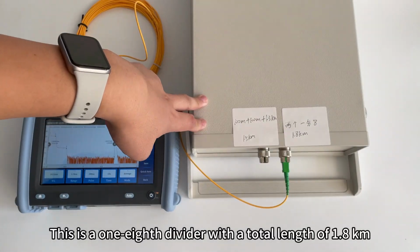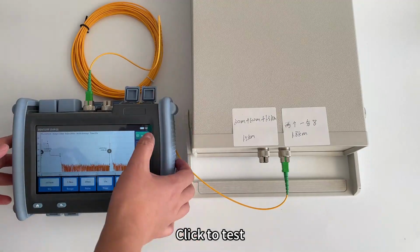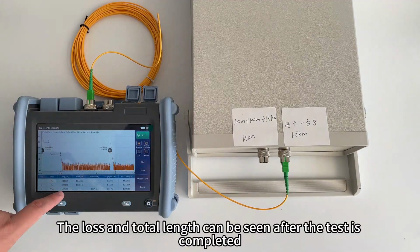This is a 1 to 8 splitter with a total length of 1.8 kilometers. Access wavelengths 1625 and 1550. Select the 1625 and 1550 wavelengths. Click to test. The loss and total length can be seen after the test is completed.